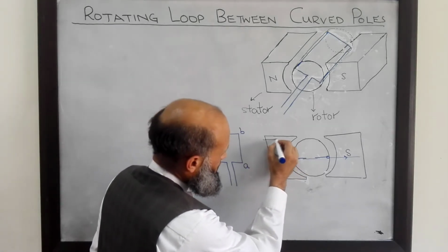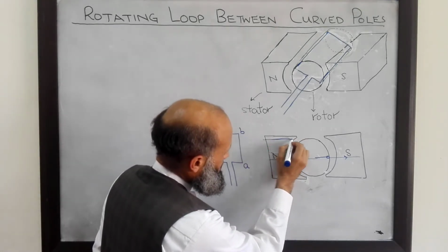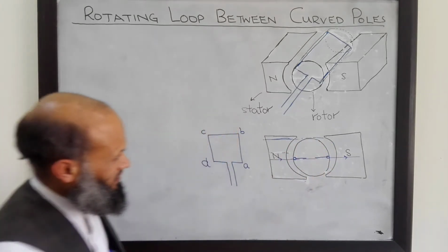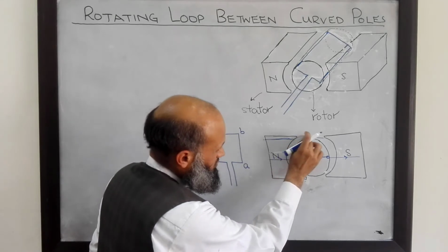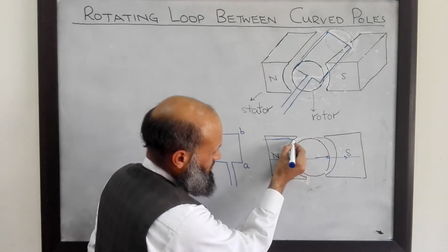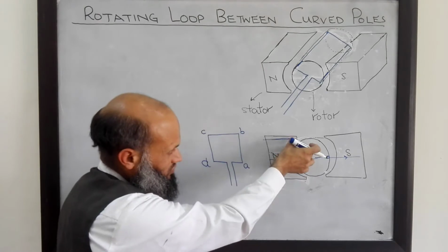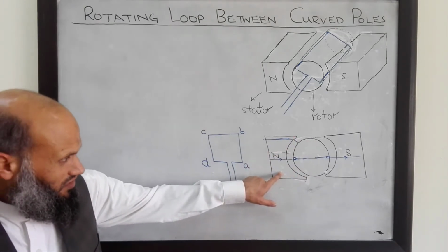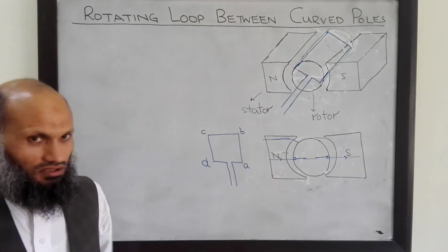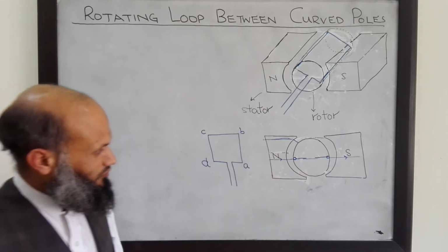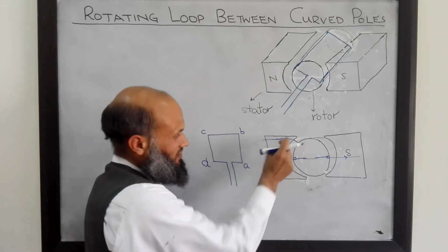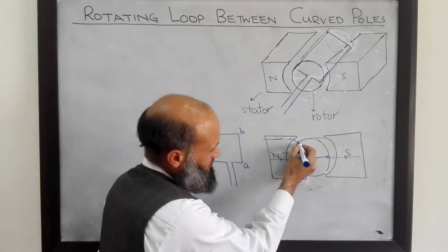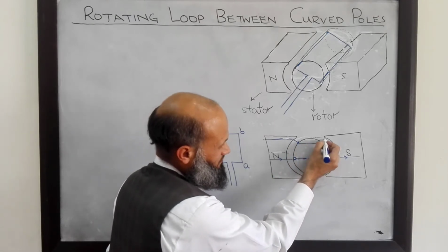So here, for example, this flux line will not follow this straight path, rather it will follow the path which has shortest reluctance. The reluctance of this ferromagnetic material and that of this core can be neglected. It is negligible. Mainly reluctance is due to this air gap, and the shortest path is from here.